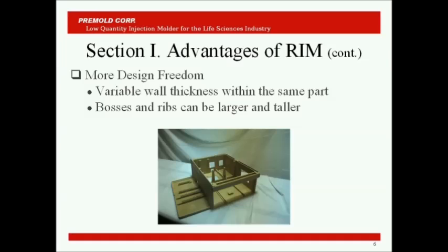Often, multiple parts can be integrated into a single part, resulting in improved cosmetics, lower tooling costs, lower part costs, and even lower assembly costs for the instrument manufacturer. High-pressure injection molding and pressure-forming processes simply do not allow these freedoms. The picture on this slide illustrates a large part with variable wall thicknesses and tall bosses.